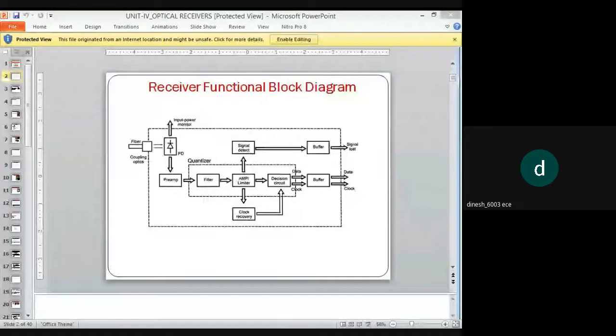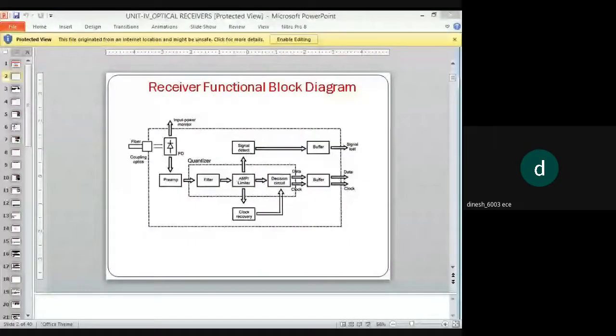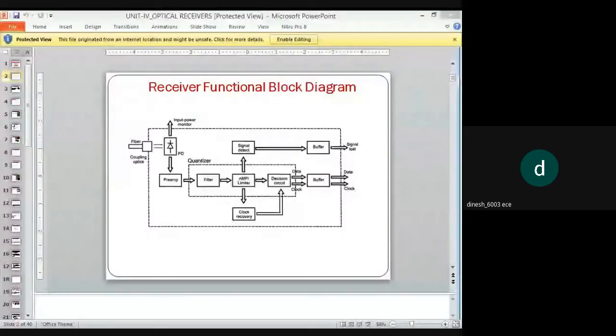This is also called the shot noise or quantum statistics. The photodetection process leads to noise. Then there is gain noise, for example, the gain process in avalanche photodiodes or erbium doped fiber amplifiers, EDFA, is noisy. A receiver circuit noise is that it will have a resistor and a transistor in the electrical amplifier contributing to circuit noise.